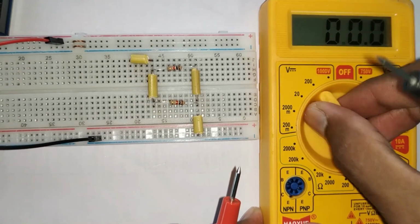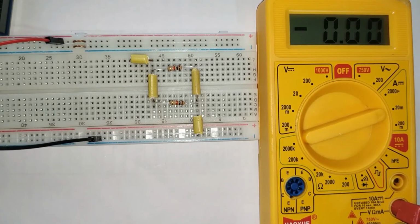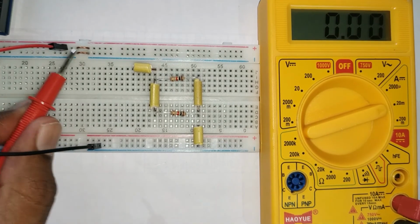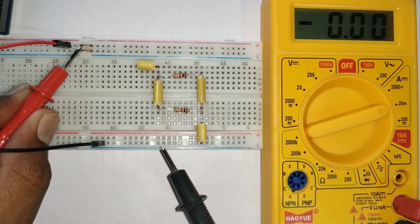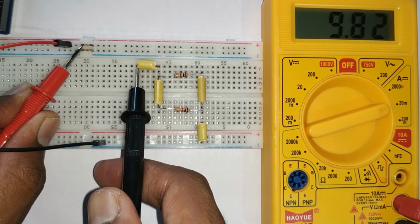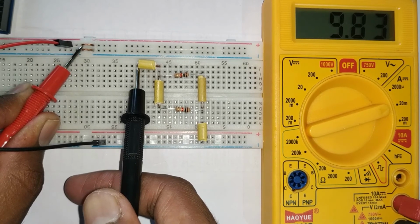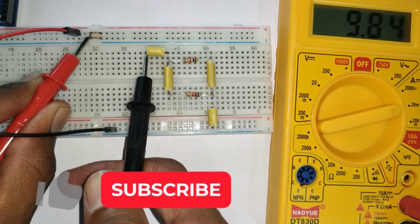First we have to set it to the amps mode. I will set it to the amps mode. What did we get? About 10 milliamps. So I will put it in the range of 20 milliamps. Now I will put one end of the multimeter to the power supply and another to our circuit. So we will get the current. Now you can see we are getting a current of 9.8283, which means close to 10 milliamps. Due to the resistor tolerance it will vary, but we are getting approximately 9.84.